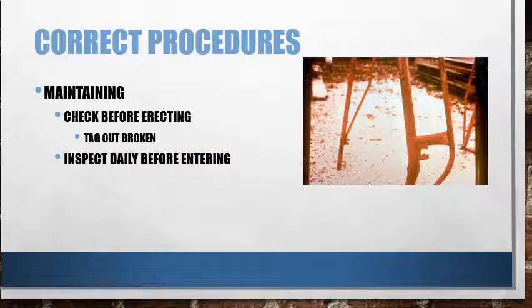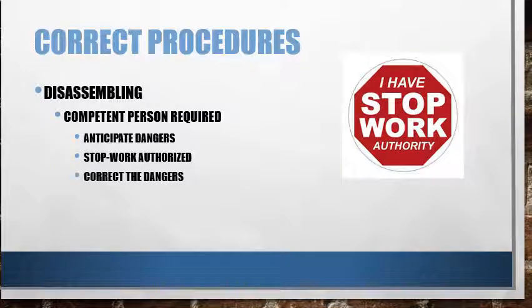Also, make sure you maintain your fall protection systems regularly. Check them before erecting them. Tag out if things are broken. And inspect daily before entering anything where fall protection or fall prevention would be needed. Same goes for disassembling. A competent person would be required to anticipate dangers, who is authorized to stop work, and then correct those dangers.